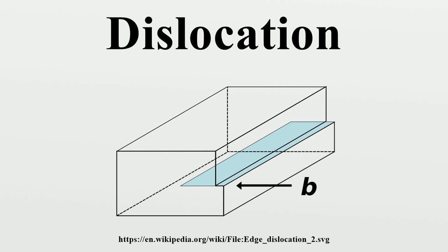Screw dislocations. A screw dislocation is much harder to visualize. Imagine cutting a crystal along a plane and slipping one half across the other by a lattice vector, the halves fitting back together without leaving a defect. This is similar to the Riemann surface of the logarithm map.